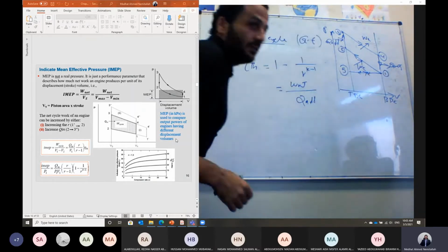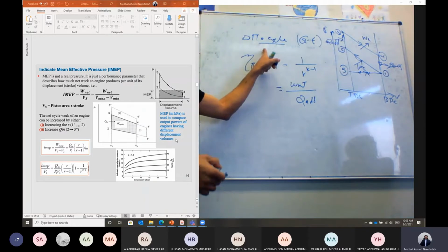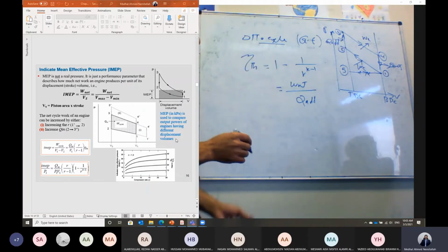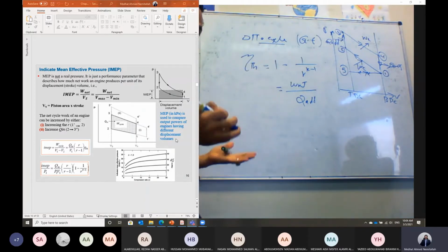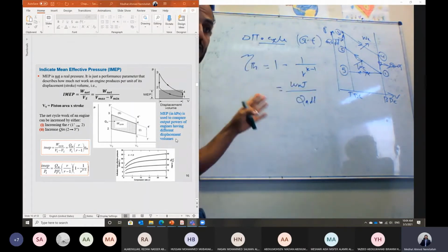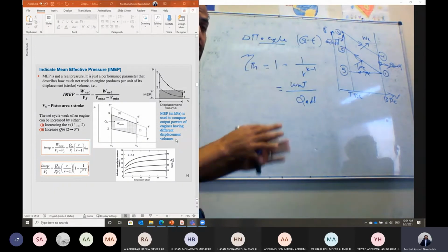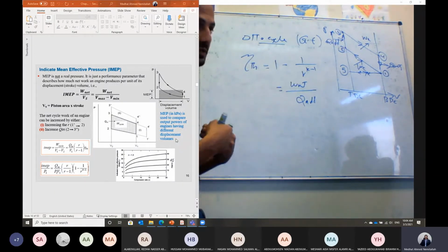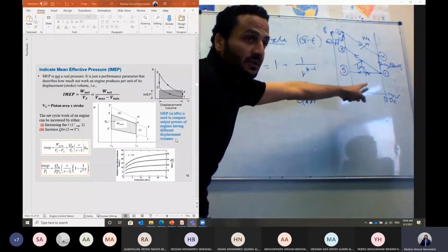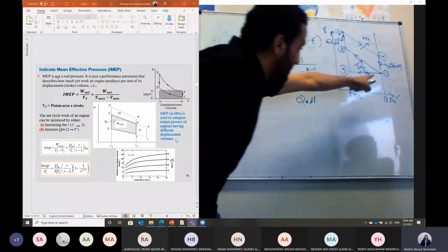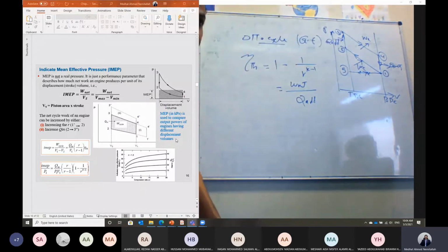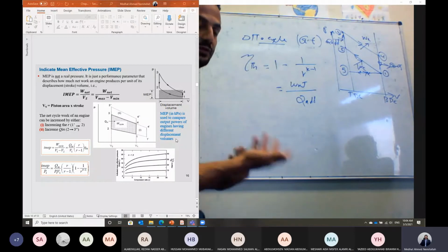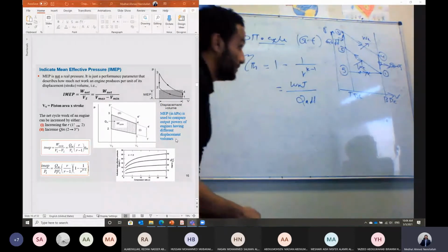This is one extra process on the standard Otto cycle, because in a standard Otto cycle we assume we don't have an intake valve or exhaust valve, and we don't have an exhaust or intake process. We just have a fixed amount of air. We don't even assume we have fuel inside the engine. So this process from 1 to 5 is just indicated to represent the case of the real engine. However, in the standard Otto cycle, we assume we don't have an intake or exhaust valve.